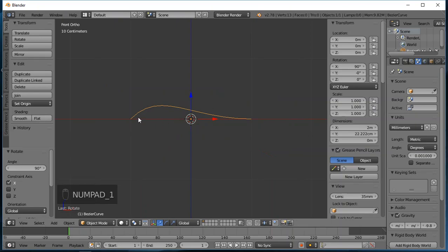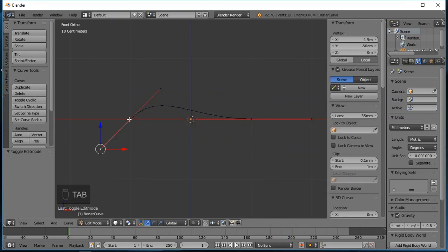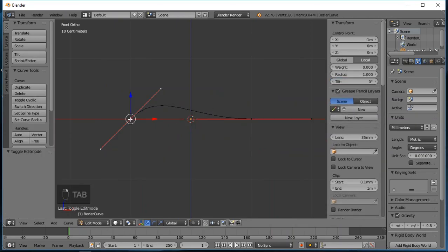Now I can see the curvature, and now I want to select that vertex, and I want to move it to 0, 0. Now I don't want to use local coordinates, so it's very important to click that global value here and set 0 in the X. Y is always going to be 0 because that would be coming in out of the screen, and we really need a flat shape here. And then 0 in the Z, and there it is.